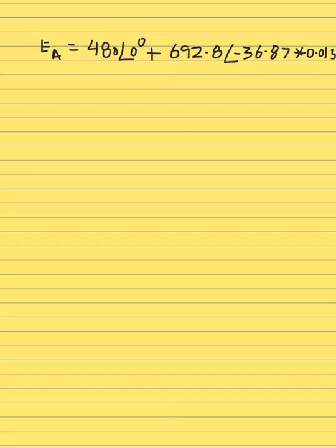EA equals, sorry, V phase, which is 480 at an angle of 0, plus IA, which we calculated, 692.8 at an angle of negative 36.87, multiplied by RA, which is 0.015, plus the next term, I times again the current, exact same value, and the amount of the reactance is 0.1.